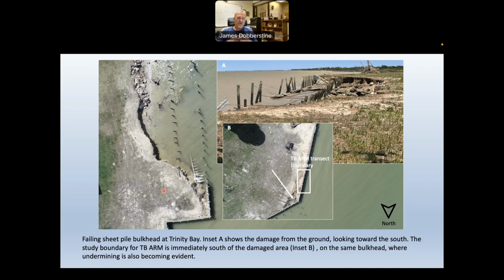Dickinson Bayou, if you were to go up and down Dickinson Bayou 15, 20 years ago, may still be that way, I haven't spent a whole lot of time there lately, there were a lot of old wooden bulkheads that were built in the 60s and 70s that are actually separated from the shoreline, because they eroded around the edges and then failed from behind. And so there's just a wall kind of out in the stream, and you'll oftentimes see cuts in the shoreline either side of where that wall had been, where that erosion was accelerated the most. Oftentimes, you can also see accelerated erosion across the stream, depending on the nature of that particular stream.